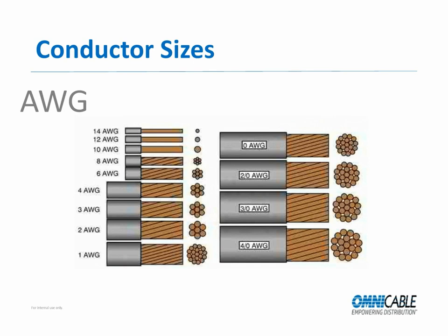The larger the diameter of the cable, the smaller the gauge size used to describe it. So a 1 gauge cable has a larger diameter than a 10 gauge cable. Next, after 1 gauge cable, is size 0. From there, more zeros are added to the gauge size to express its diameter. So the next largest size would be 00.